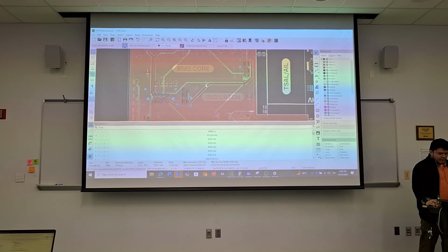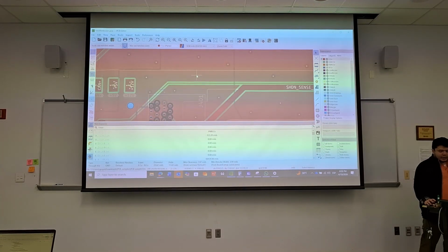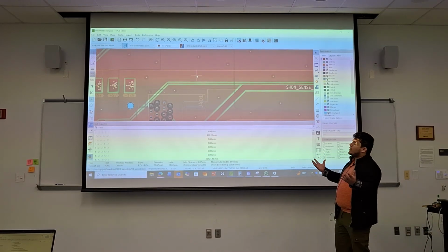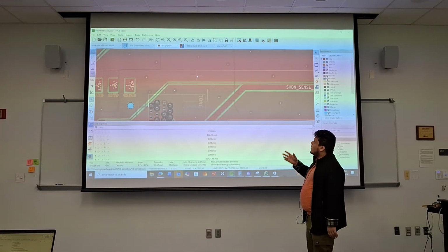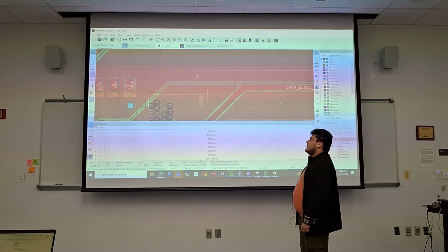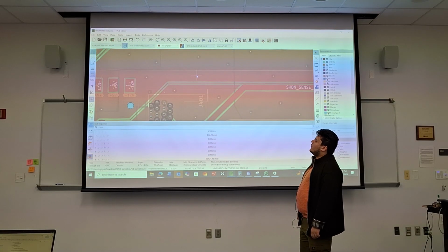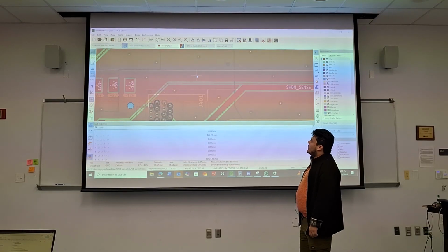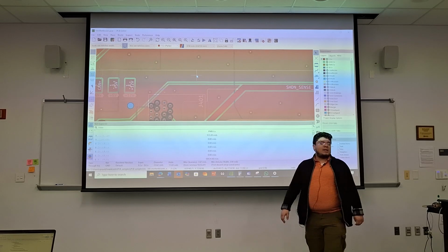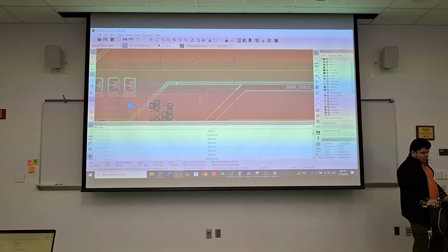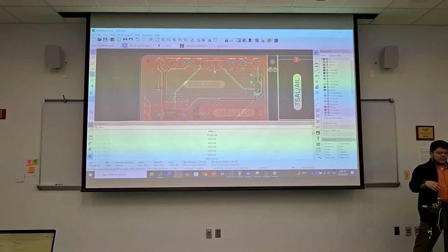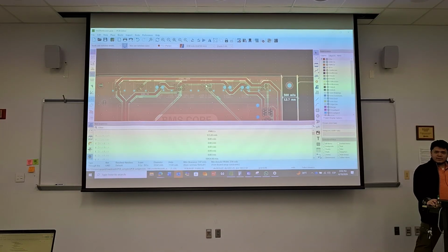I like the shielding that it has, but I would say it could be better because, depending on the frequency of the board or the frequency of everything, those vias should be a lot tighter, right? Maybe not a quarter of a wavelength, but it should definitely be at least a wavelength, stitching all the way across. I do notice, so is what you're measuring outside, or is it just that the signal integrity inside is not great?